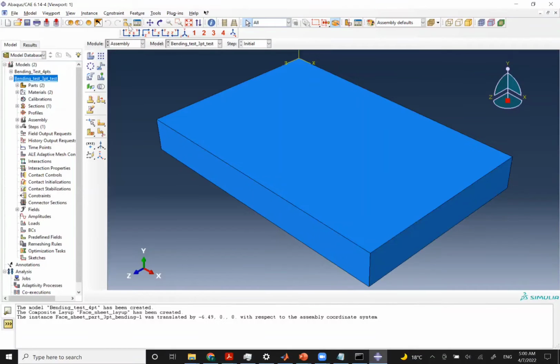But before that, it's really good to get familiar with this option here, with this feature. As you can see, once we added these layers together, it's hard to see which is which. So if you go to here, it says remove selected. You click on it, and then you go down there, and you select what faces or cells that you want to remove, or you want to hide, not remove.